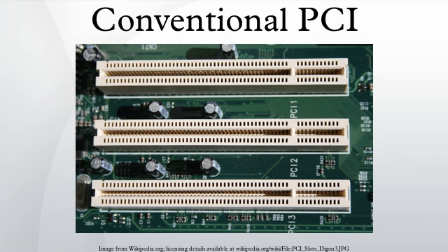A server-oriented variant of conventional PCI, called PCI-X, operated at frequencies up to 133 MHz for PCI-X 1.0 and up to 533 MHz for PCI-X 2.0. An internal connector for laptop cards, called Mini PCI, was introduced in version 2.2 of the PCI specification. The PCI bus was also adopted for an external laptop connector standard, the CardBus.